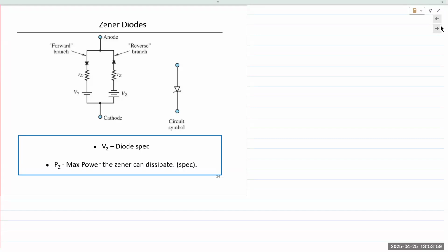So I believe we covered conduction in the reverse bias due to minority carriers, two effects, Zener and an avalanche effect. Do you all recall, remember? So in the reverse bias, you have minority carriers that are able to pass through the junction, right? The voltage across the junction keeps on increasing until a point is reached when the electric field causes new free charge carriers to be generated. So you have a reverse bias junction.